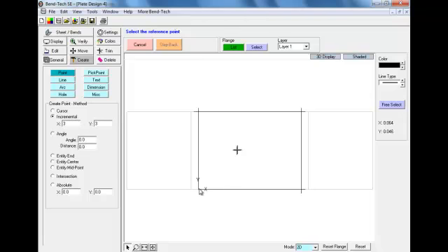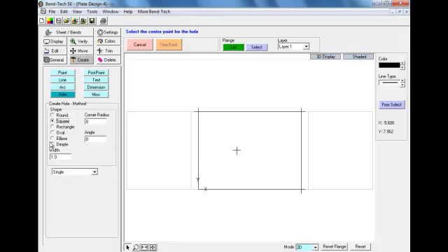Our first point is going to be created using the incremental version, and it is going to be 3 inches in the X field. We're going to add 3 inches in the Y field, and we're going to create a point in that location on the base flange. Then we can go ahead and create a circle on that point.